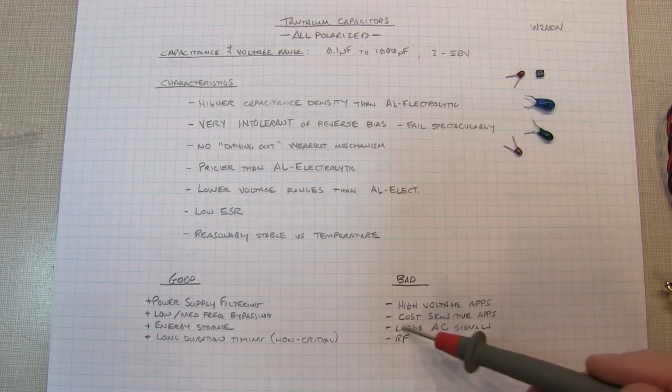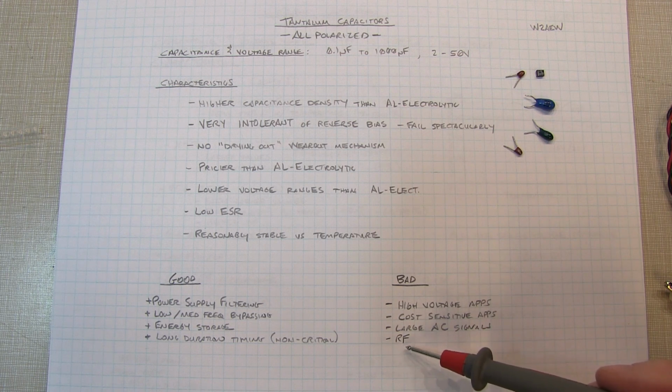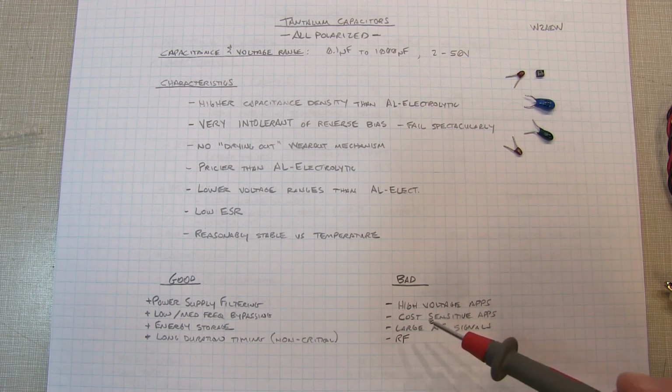And similarly, their self-resonant frequency is low enough that you're not going to really use them too much for RF applications, although the ESR of them is a little bit better than it is with the aluminum electrolytics.